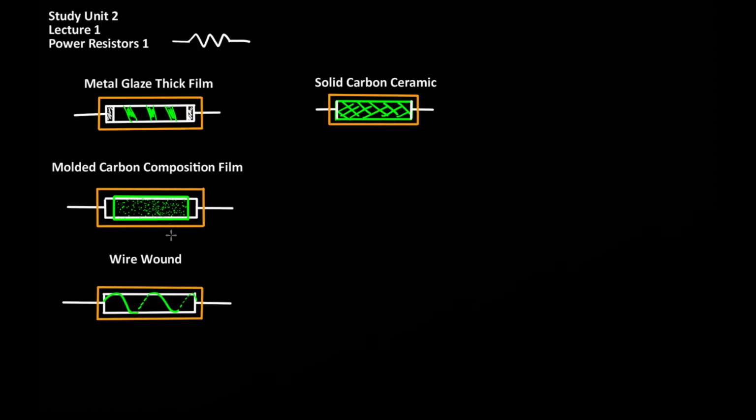In terms of power electronic specific circuits, power resistors are used in series RC networks, in series inductor resistor networks, RC snubbers, current sensing, resistor dividers, voltage and current damping, and so on. Depending on the application, there are several resistor types which can be used.